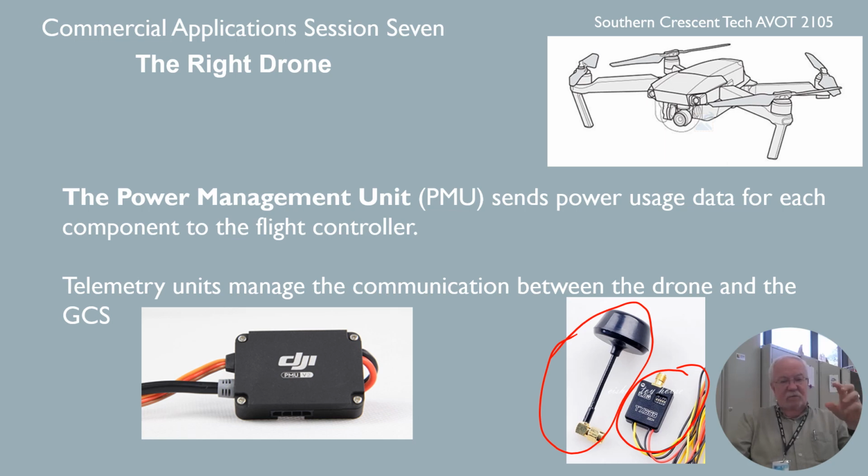That's why we have those automated triggers, where if you lose connection between the ground control station and the drone, and it's doing some automated flight plan, it'll finish that flight plan and then fly back. If you're just flying around and all of a sudden you lose connection, you don't need to panic, because perhaps it'll wait a little while and try to reconnect, or maybe it'll just immediately go to the return to home altitude, fly back and land in front of you. Or sometime during that return to home, it'll reconnect, and then you just continue doing what you're doing.